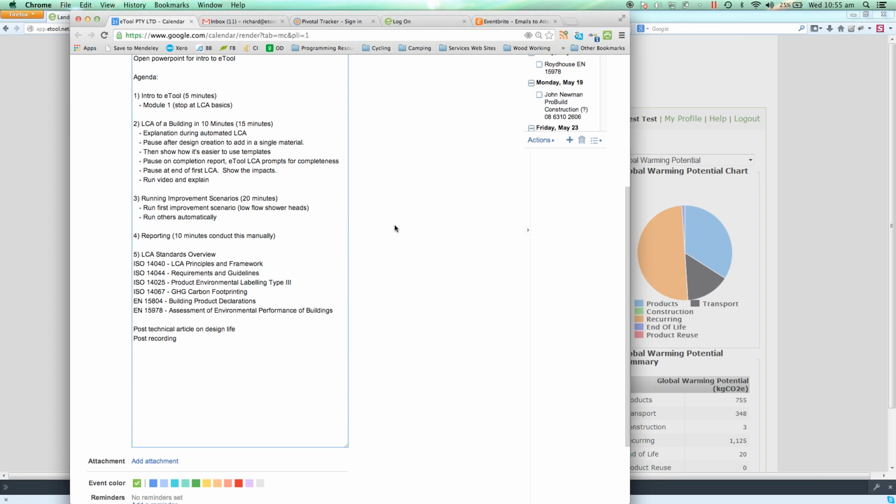You said you've been trained in NatHERS as well. Is that right? Accurate, yeah. And what we find is for Perth climate, insulating the thermal mass, so having the insulation on the outside of the building, is a very good solution. It's quite easy in Perth to design a building that doesn't really need heating and cooling, just natural ventilation, like you mentioned, and create an orientation to benefit from some solar gain, and insulate it well, and have thermal mass on the inside.